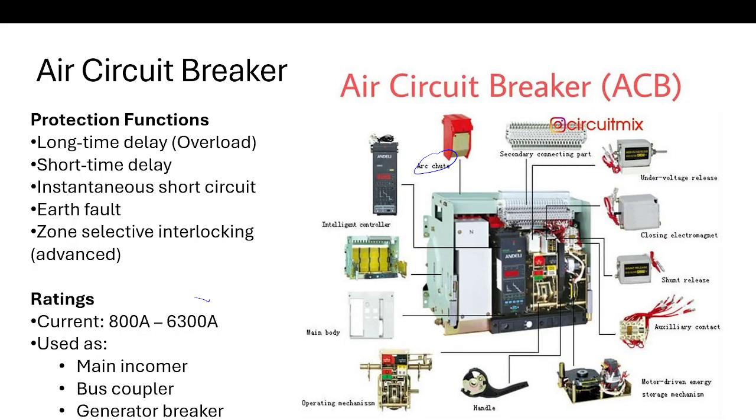Now, there are certain types of circuit breakers. Plain break ACB: simple arc interruption in air. Magnetic blowout air circuit breakers use a magnetic field to move the arc. Air chute circuit breakers use arc chute plates to split the arc. And air blast circuit breakers use high pressure air. This is used mainly for high voltage, and these are very less common today.